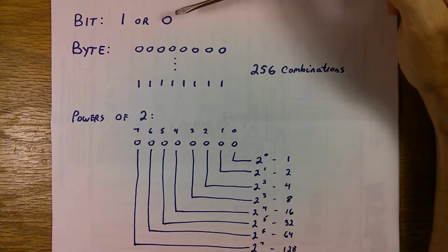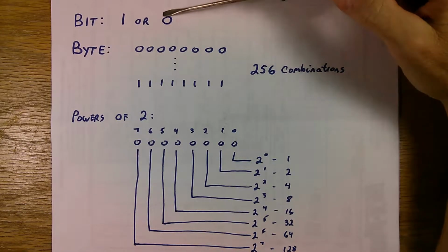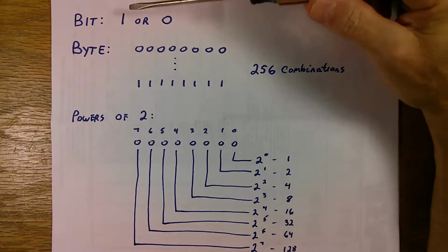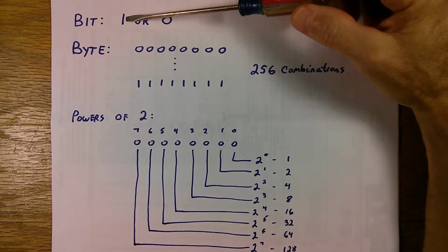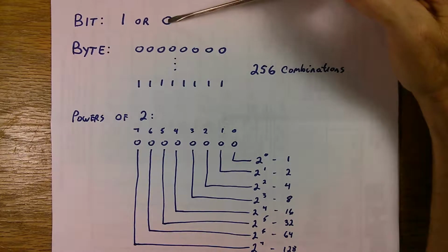Now, I don't know exactly what's going on inside of, say, the ATmega, what the different voltage levels are inside on the chip itself, but on the I/O pins, a 1 is represented by a high voltage, and if you're running your microcontroller on 5 volts, it's generally a voltage higher than 3 volts on a pin would represent a 1. And a 0 would be represented by a voltage below about 1.5 volts.